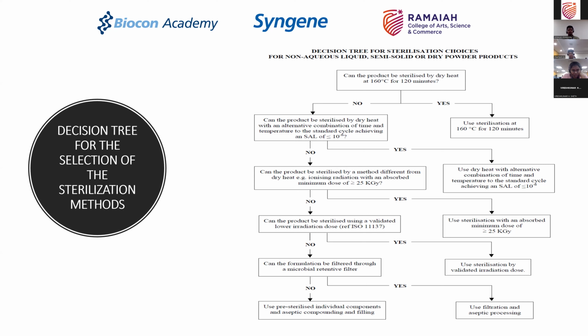So now you've got the solid, you have to dry it, you apply vacuum, load it into a VTD or a vacuum tray dryer or something like that. Now, there are equipments available where you can filter the solution, remove the liquid, dry the powder within the same equipment without removing it, and then take it out as a dry powder, which can be directly filled into vials in a sterile method.